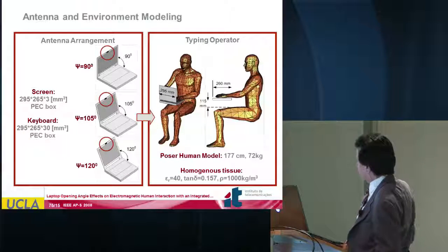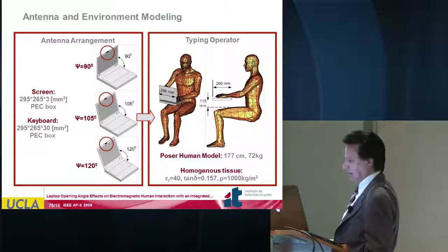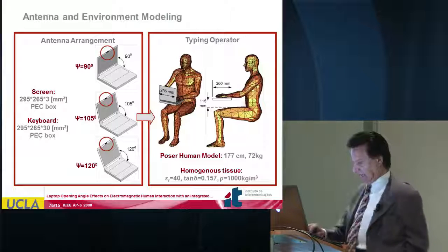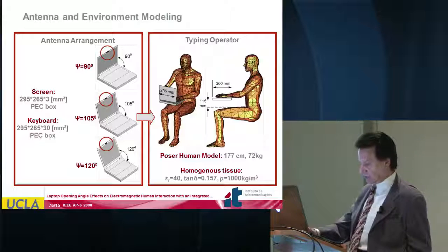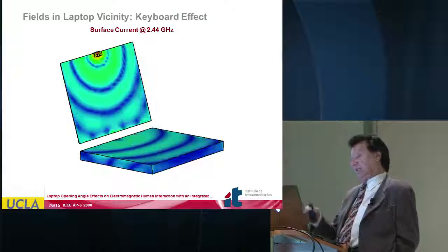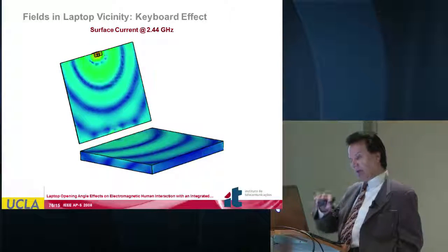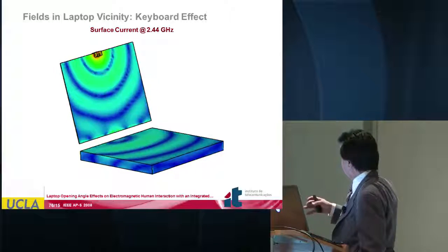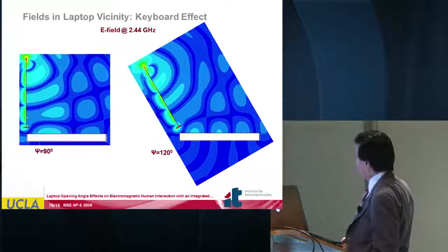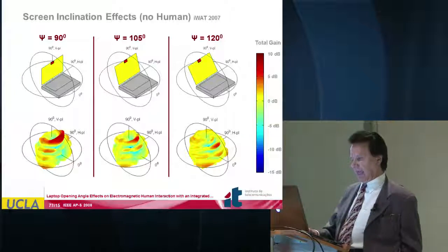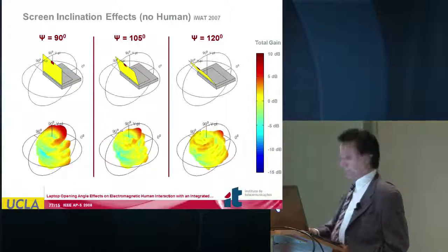And we look at a bunch of scenarios, how you open your laptop, what angle you open your screen, and so forth, and its effect on the performance. So this was a collaboration with a team at one of the universities in Portugal. So we have a lot of collaboration of this nature. So this gives you, again, the feeling when this antenna was mounted, how the radiation, how the electromagnetic currents propagate on your laptop, and how the radiations occur from different pieces of the laptop. And again, as we noticed, how the overall performance can be observed.